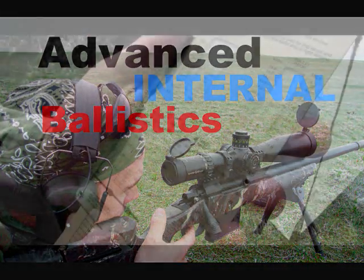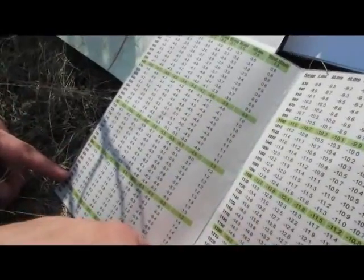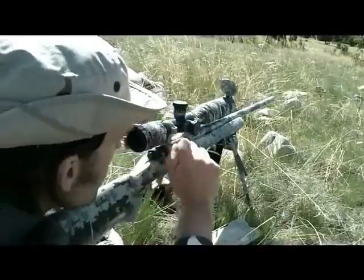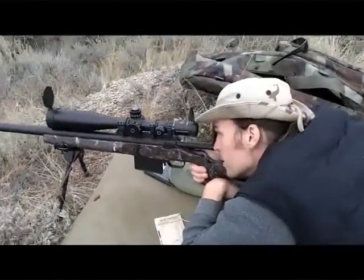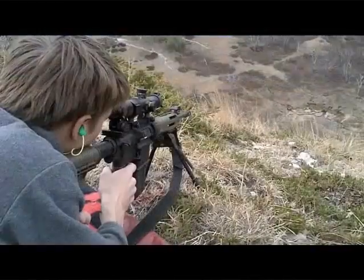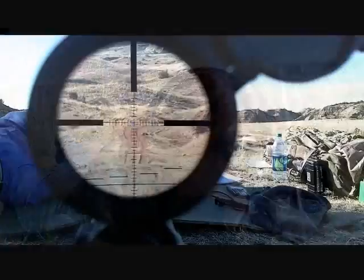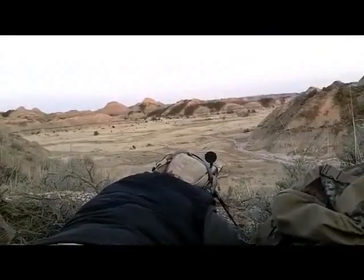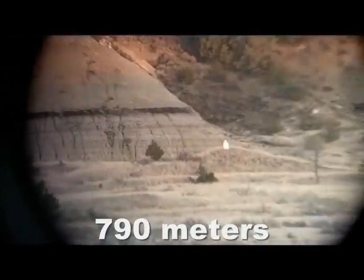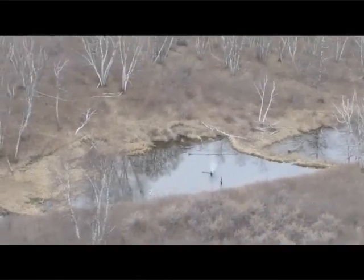So that's another major reason why most guys do go for free floating the barrel, because then you can't introduce tension to the forearm of the stock. And the point of the stock up there is you have a rest. You can lean it against something, you can hold it with your hand, you can deploy a bipod, and it's not going to directly affect the tension against the barrel. It's still going to throw off your harmonic nature of the entire rifle system, as we'll see in a minute here, but it's not going to directly affect the barrel part, which can really throw you off.